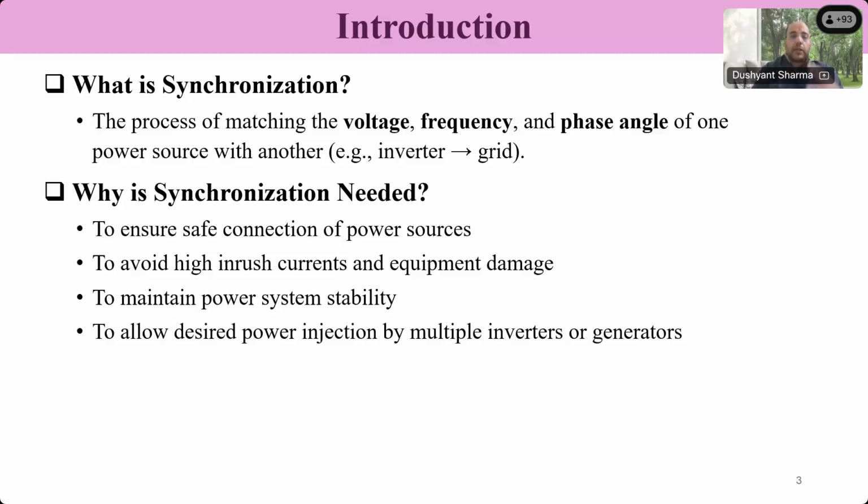That means if you can recollect the phasor form, if you have a phasor that represents the bus voltage where an incoming generator is to be connected, then the phasor of the incoming source has to match the phasor of the bus voltage. Once you match the phasor of the incoming generator with the phasor of the bus voltage, both are the same.